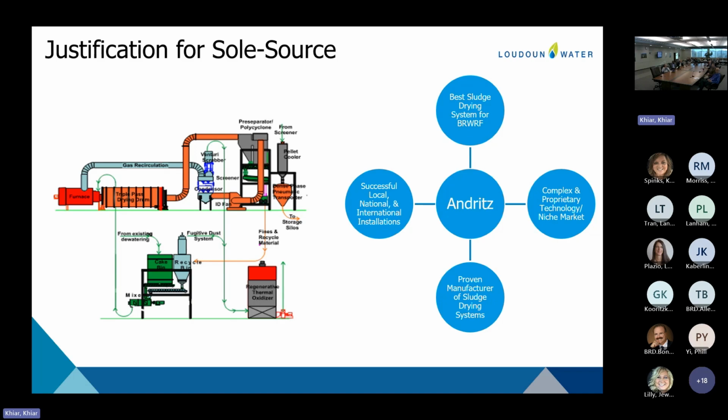The 10%, you have a small portion of air that is pulled off. It runs through a scrubber to get the rest of the particulates out. And then it goes down to a regenerative thermal oxidizer, which basically just oxidizes out VOCs and odorous compounds. And then the 10% that you take out is replaced by the combustion air that's added to the furnace to support the flame. So you have kind of a balance there with what's taken out and what's added in. In a nutshell, that's generally what's happening in the dryer system. Again, there are many more complex supporting systems that aren't really shown here.